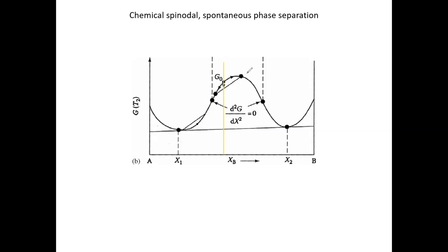We know that in actually all of the phase transformations, the separation is always initiated through fluctuations, right? And then the thermodynamics is going to play a role to stabilize these fluctuations or destabilize them. So here we have the same thing. Initially you have a very homogeneous mixing of the system. If you look at a small portion, it's going to be uniformly mixed, with a composition of X naught.